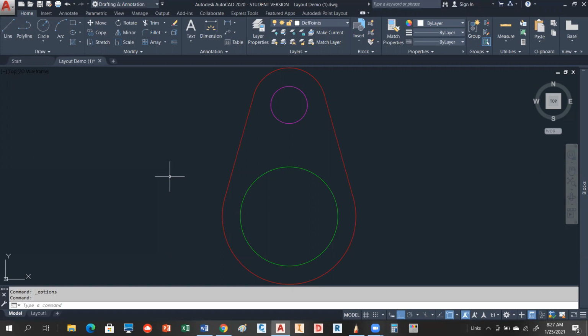Because one of the things about viewports is you typically never want to print them. It's kind of like you don't really care that those are out there, and you don't want somebody else to see what you've done with them. It's just stuff that you don't want to share. So think of them also, as we create these viewports, besides being an object, think of them as a camera object. And each viewport's going to be a camera that's going to be focused on the model at some view and also at some scale factor representation.